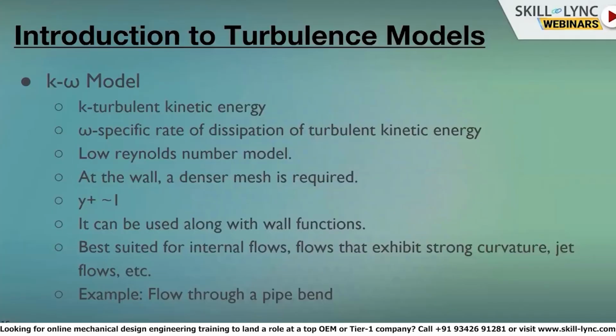With the computational mesh, we require a y plus value approximately close to 1. Sometimes it can be used along with wall functions also. There is no harm in that. So in those scenarios, we can go for a slightly higher y plus, around 10 or 15, and then the wall functions capture the near wall phenomenon and bridge with the log-law region.